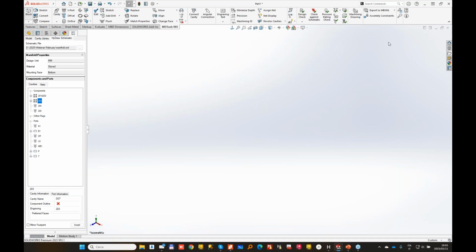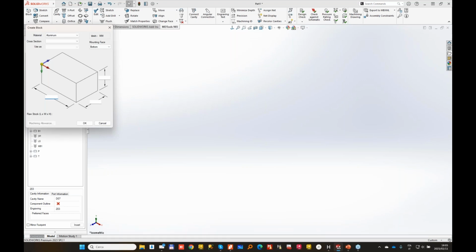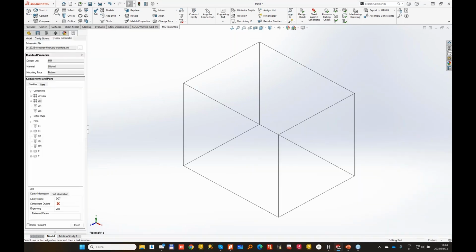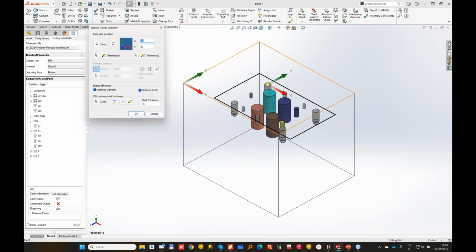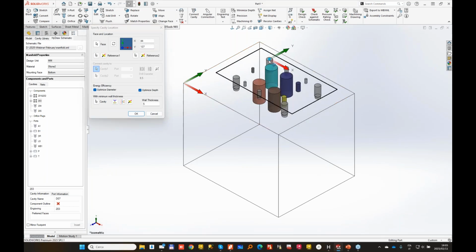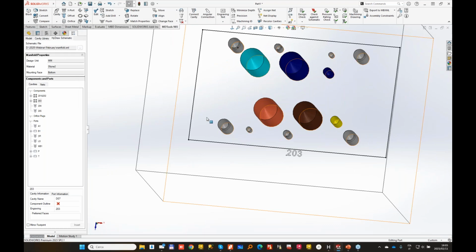So let me start a block, and let me make, let's say, 200 millimeters by 160 by 160, then we'll change accordingly. Like I was mentioning, one enhancement is related to the position for the engravings. If I place a footprint now, my DO7 footprint, in the past, and this is applicable to Inventor as well, not only SolidWorks, the default position for engraving is within the boundaries.